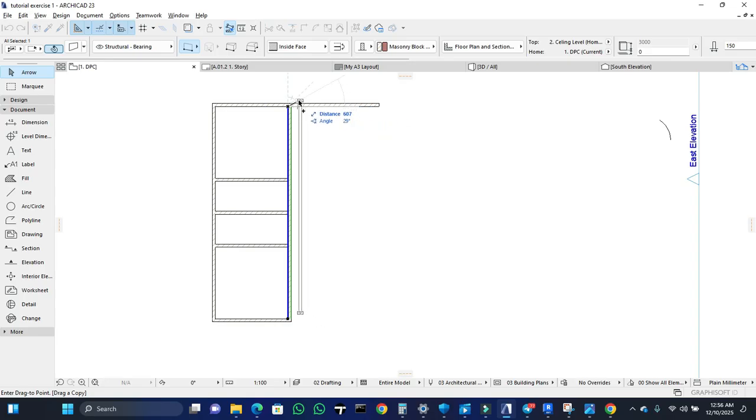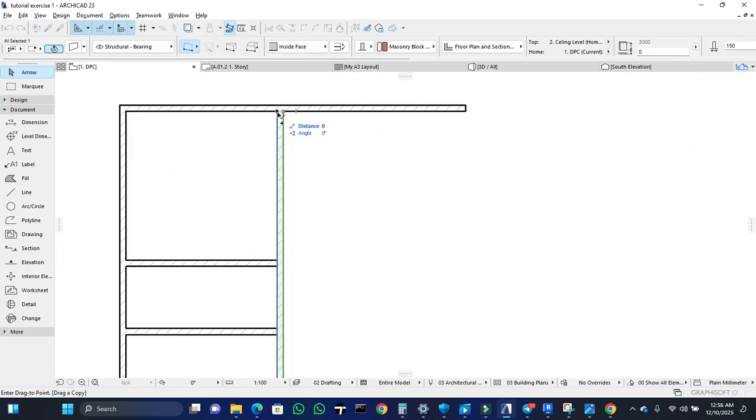Now always note that if you want to drag 3 meters from the original point and you want the internal dimensions to be what you are imagining, which is 3 meters, make sure that you include the wall thickness in your offsetting distance. While I want to type the distance with the internal dimension in mind, I will know that what I should be typing is 3,150, not just 3,000.